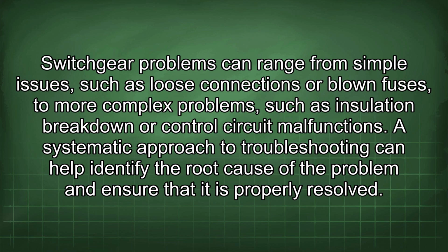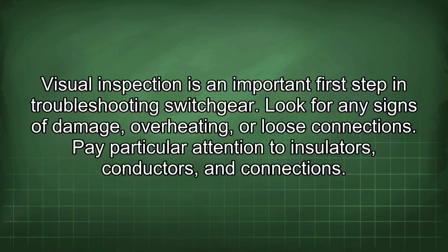A systematic approach to troubleshooting can help identify the root cause of the problem and ensure that it is properly resolved. Visual inspection is an important first step in troubleshooting switchgear. Look for any signs of damage, overheating, or loose connections. Pay particular attention to insulators, conductors, and connections.